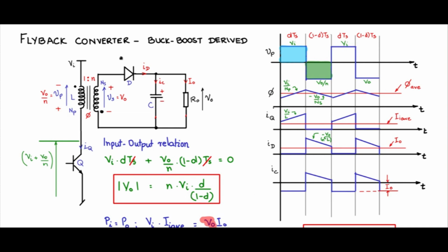In this fashion we have the flyback converter, and this is the functional schematic of it. It is very, very popular. You can also have multiple outputs. You can have multiple secondary windings wound across the inductor, and you can take out isolated multiple outputs from this flyback type converter.